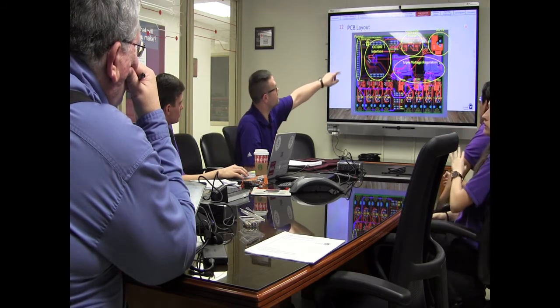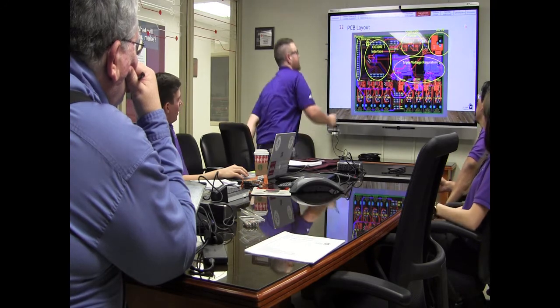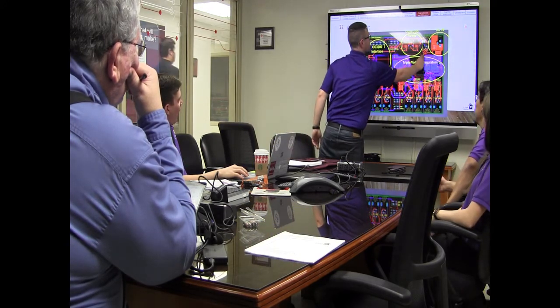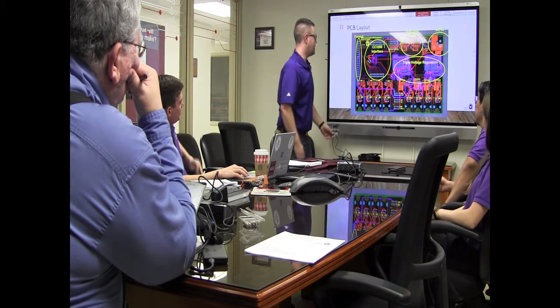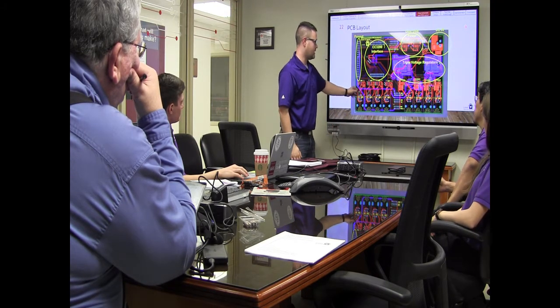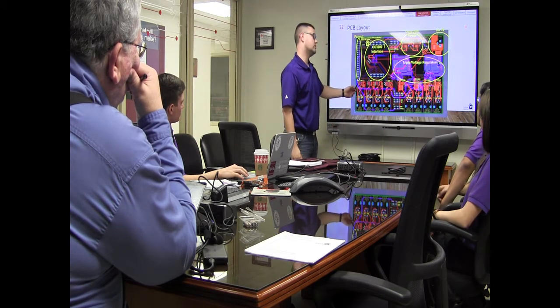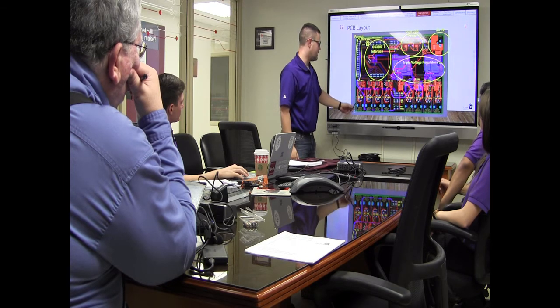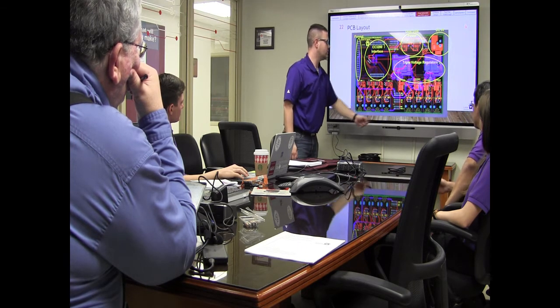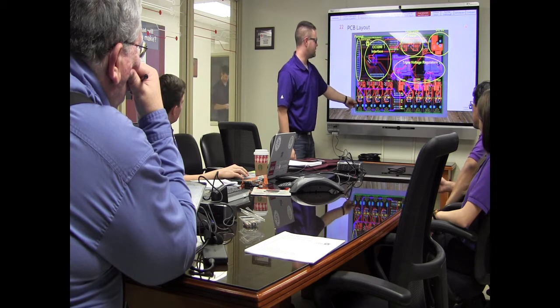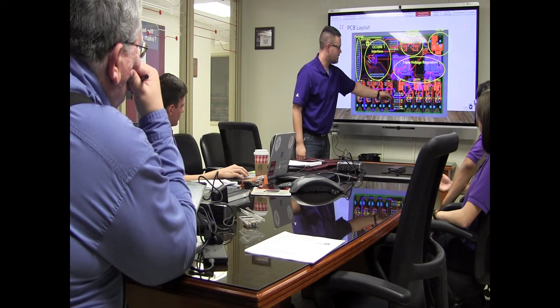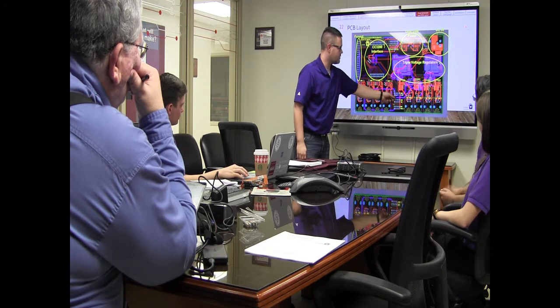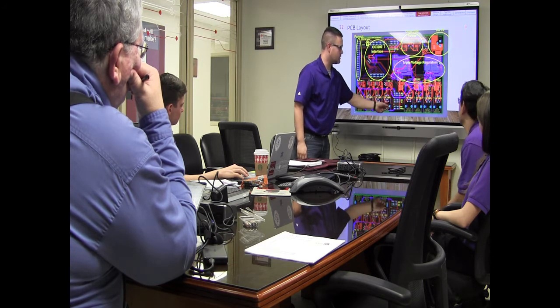They have their own special port. Right up here, this guy is the sensor port, and then here's 4 low side switches, or dual low side switches actually, and then here's port 1, 2, 3, 4. Those are all low side switch with the selectable 12 volt or 5 volt DC with just a little shunt bar. And then here's all of our voltage outputs. So one stripe is ground, next one's 3.3 volts, next one's ground, one's 12 volts.